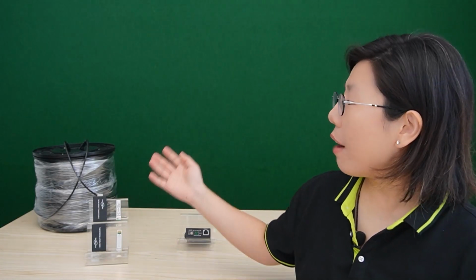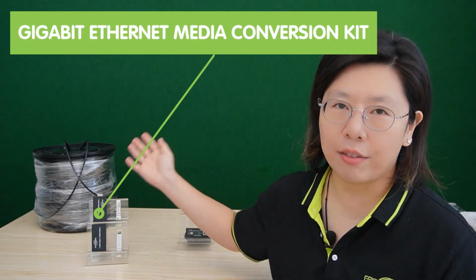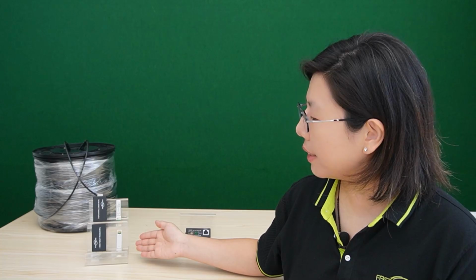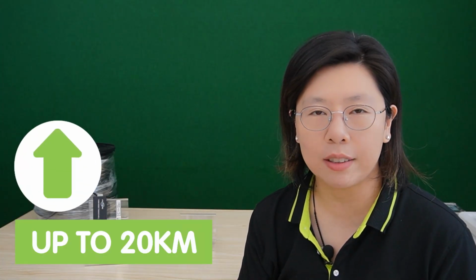And next to it, we have our Gigabit Ethernet conversion kit. Now this kit includes 2 media converters and 2 SFP transceivers, power adapters, and a 300 meter pre-made fiber optic cable. By leveraging the benefits of fiber optic, this media conversion kit allows you to transmit data up to 20 kilometers at a data transfer rate of 1000 megabit per second.